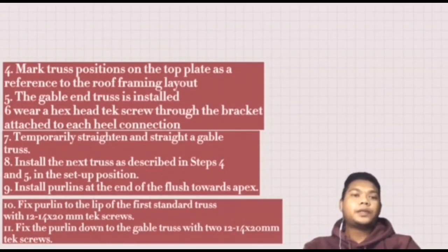Fix the purlin to the lip of the first standard truss with a tek screw. Fit the purlin down to the gable truss with a tek screw.